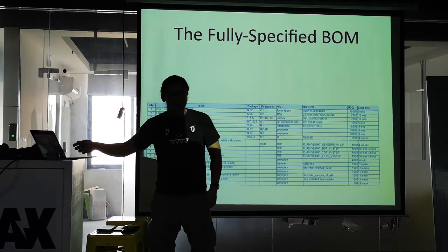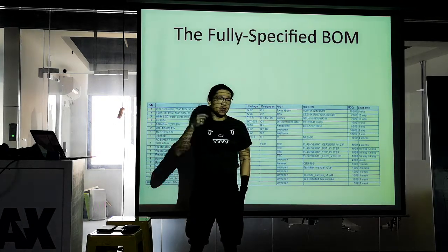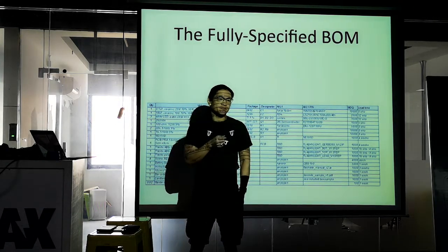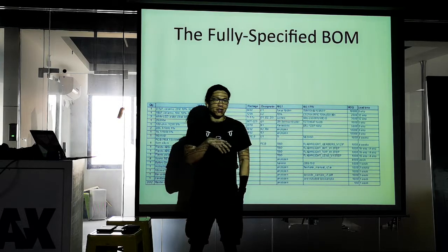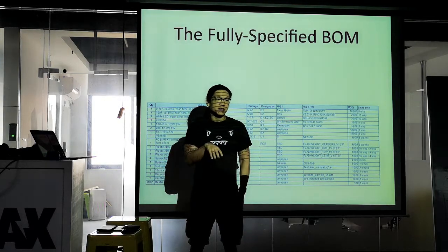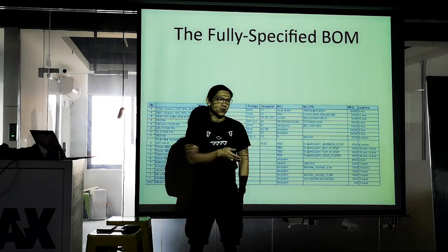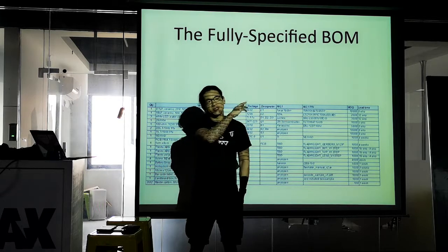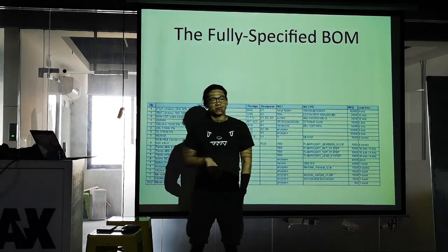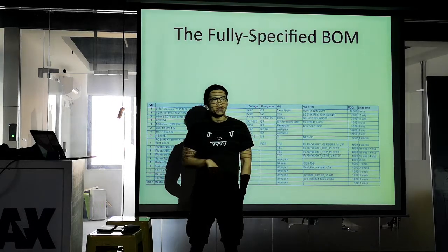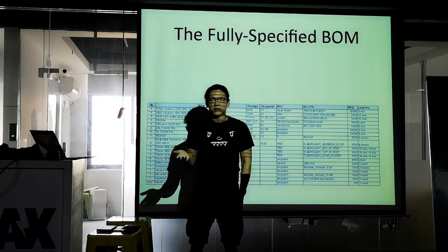You can specify. So if you order, you can tell them, look, if I'm doing a small run, and it's a prototype run, I want you to buy full reels. If your intention is you're going to build more of them, typically tell them to hold it, right? So we're going to go into mass production shortly. If you're just doing a prototype run, you say just give me all the reels after it, send me an invoice, right? Because most of you are not planning to go to thousands of unit scale.